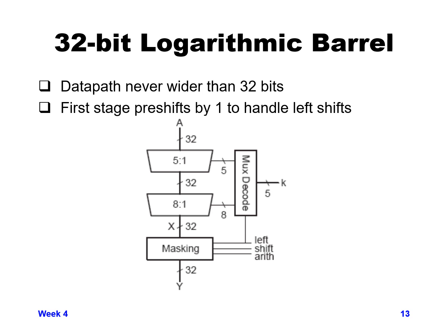And in this case, the 5-to-1 multiplexer can either rotate by 0, 1, 2, 3, or 4 bits. This will handle a potential pre-rotate by 1 bit, followed by a fine rotate of up to 3 bits.